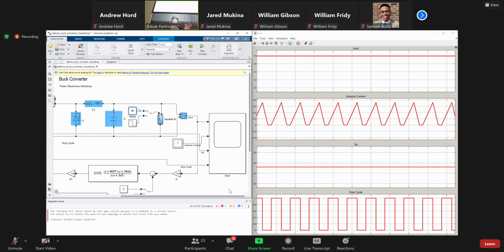So what are the other parameters that affect this? So many things. Load, inductor value, switching frequency, right? That's it. And therefore, because it's a combination of these, we define a parameter that we call the tendency of the converter to operate in DCM or CCM. It's a very qualitative term because it doesn't depend only on one parameter.